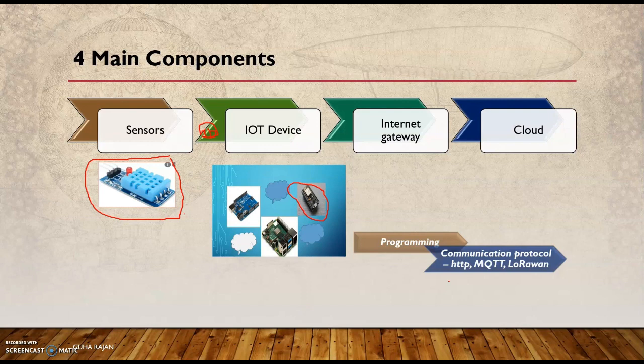The protocol means a handshake needs to happen, through which the data can be sent across from the IoT device using Wi-Fi through the internet gateway to the cloud system, where you have a computer that is going to receive the data. There are freeware cloud systems like ThingSpeak, and My Devices is widely used for data capture from IoT devices. Others like Amazon, Google and Oracle also support IoT devices, but ThingSpeak and My Devices are designed exclusively for IoT devices.